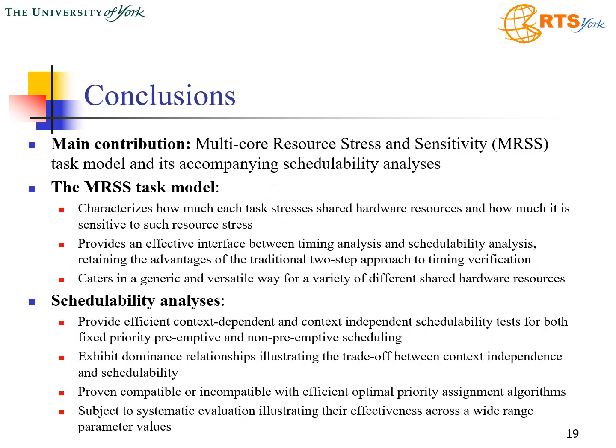In conclusion, the main contribution of this work is the multi-core resource stress and sensitivity task model and its accompanying schedulability analyses. This task model characterises how much each task stresses shared hardware resources and how much it's sensitive to such resource stress. The task model provides an effective interface between timing analysis and schedulability analysis, retaining the advantages of the traditional 2-step approach to timing verification.